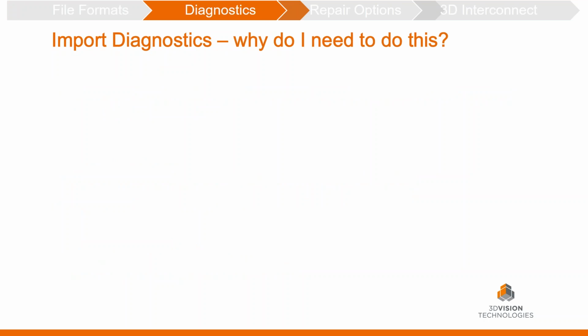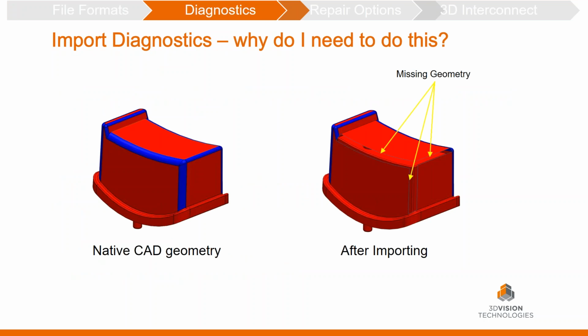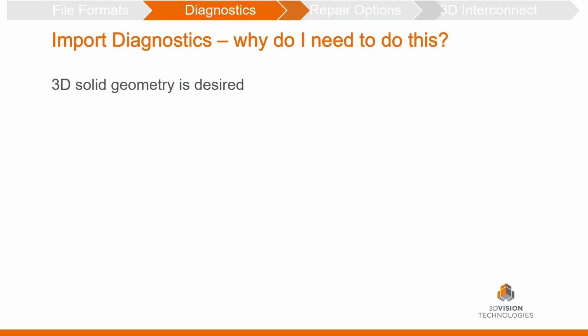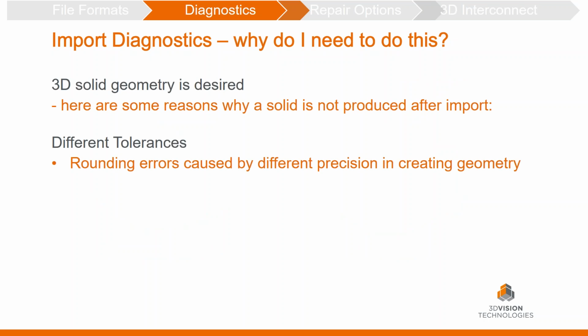Let's switch gears and talk about diagnostics. So why do I need to do import diagnostics? Well, if you look at your native CAD geometry, and then you look at it after importing into SOLIDWORKS, if you see that you're missing some geometry, that would be a pretty important thing to be aware of and also to fix. So we have some tools built into SOLIDWORKS to deal with this. Our goal is to get three-dimensional solid geometry, and as I mentioned, there are times when that might not be possible, and here are some reasons why.